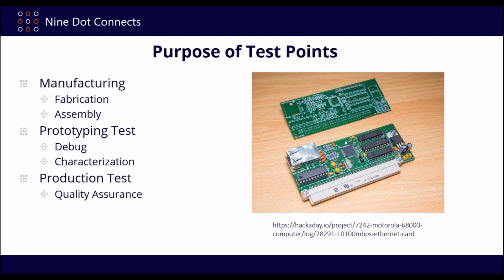So for those who maybe have not seen this or just want a quick refresher, fabrication is the actual creation of the board. When they're done with fabrication, the only thing you're going to have left is just a board here. They'll have the silks, and they may put down some type of material over the copper to prevent it from corroding, but they're not going to stuff it with any components. And what they'll probably do, more than likely, if you ask them to, is some type of continuity check to make sure that the copper was properly etched, because this is actually a subtractive process. And if you want to see more about that, we've talked about those in prior webinars.